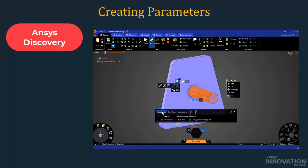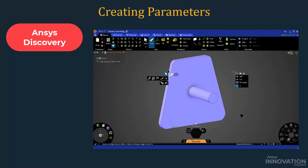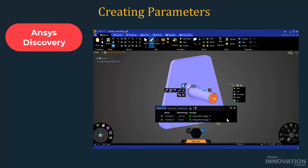The second method is to use the ruler to parameterize the distance between 2 points. For example, select the pull tool and click on this surface. Now click on ruler and select the starting point for measuring the distance, and then click on this symbol to parameterize the distance. We see the second parameter being added to the list.